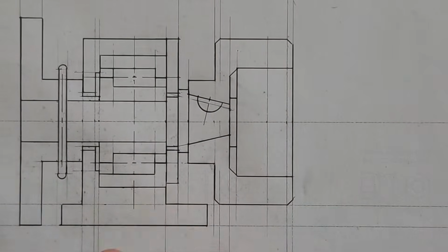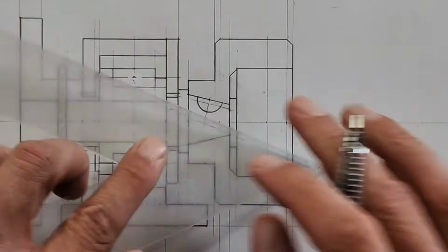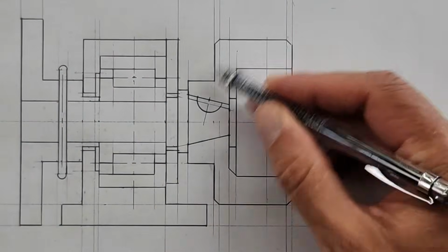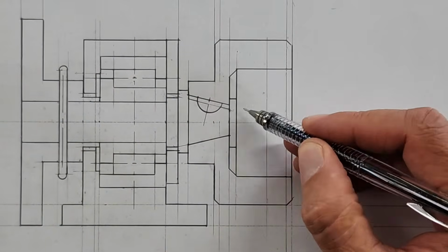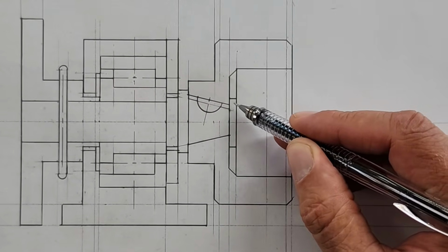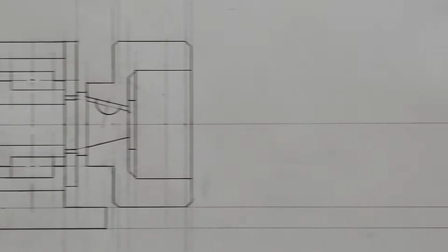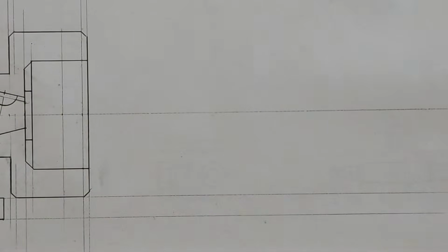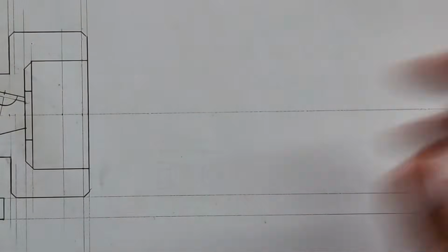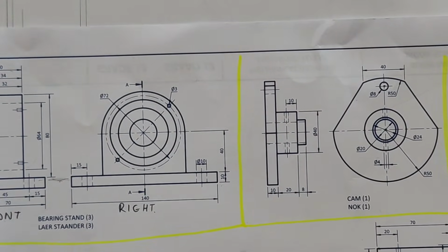All right, so I'm wanting to do the hatching with you. So I'm just going to quickly look through this drawing. We've just inserted the Woodruff key here. Just finishing off that. I've got my pulley. I still need to do my washer, my actual shaft end, as well as the nut. I'm going to use the right hand view, so I'm going to slide myself over here to do the right hand view. That's 114 total, so I'll be using these measurements. Just draw this in basic steps as a start.